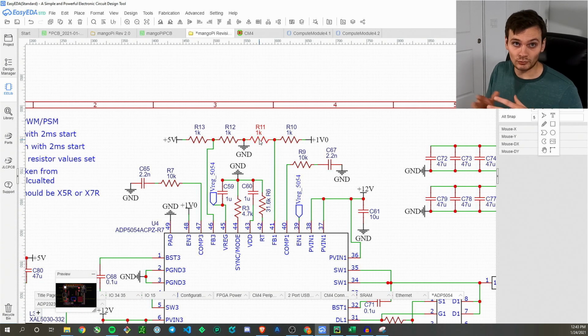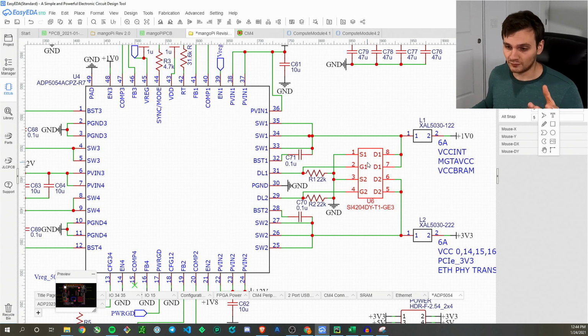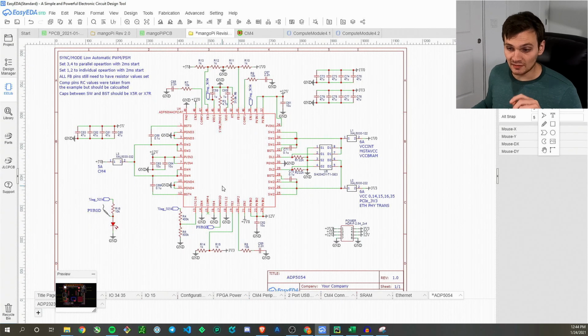I'm actually going to draw out the rest of the schematics, and then we'll come back to this and see what resistors I've used elsewhere in the board and then try to use them here. And essentially all this IC is doing is turning on and off a switch really, really fast. We have an integrated circuit here that is basically 2 electronic switches. It's a dual N-channel MOSFET integrated circuit, and this IC's job is to turn on and off these switches whenever the power supply needs more power or less power. It's a fine balancing act, but that's essentially all this is doing. And that sums it up for this one.